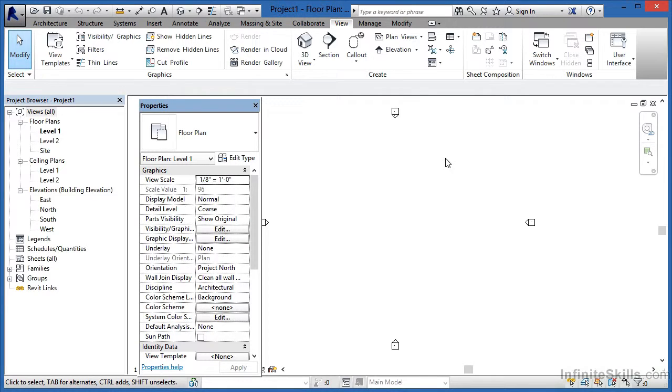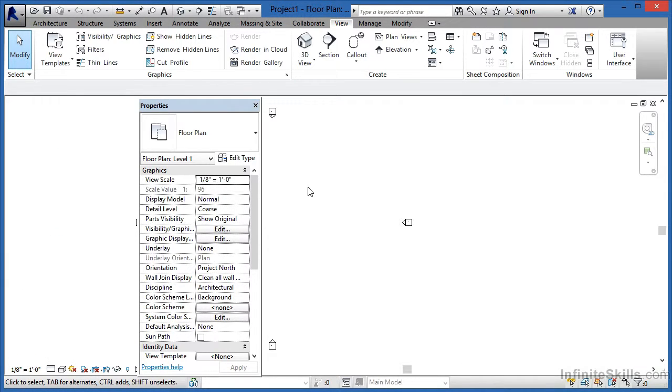So as a result of that, you can do all of your drawing on one monitor. And if you have a second monitor, the project browser and properties can be over there on the other monitor, just sitting out there in space. Also, if you do like the fact that those two were docked on top of each other the way that they were, I want to point out that there's an interesting thing that can accidentally happen. If you're moving around and you're starting to activate commands up here on the screen, you may accidentally click an X in the upper corner and close one of them down.